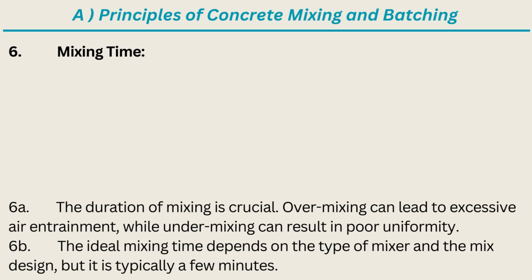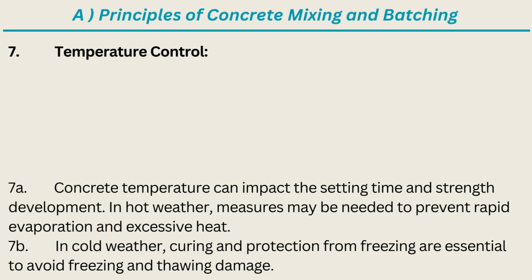6. Mixing time. 6a. The duration of mixing is crucial. Overmixing can lead to excessive air entrainment, while undermixing can result in poor uniformity. 6b. The ideal mixing time depends on the type of mixer and the mix design, but it is typically a few minutes. 7. Temperature control.